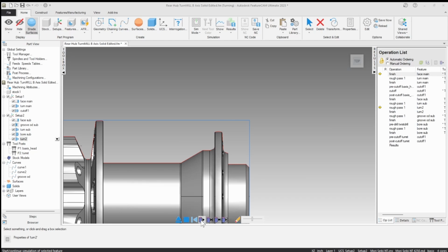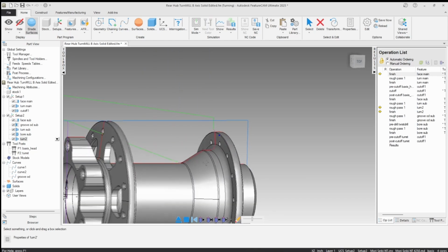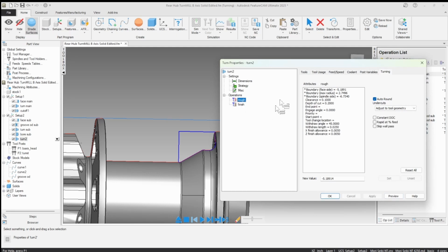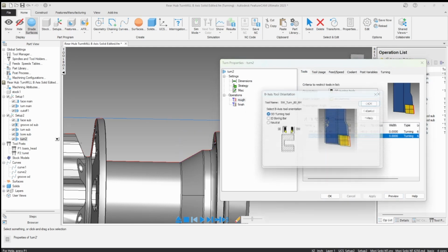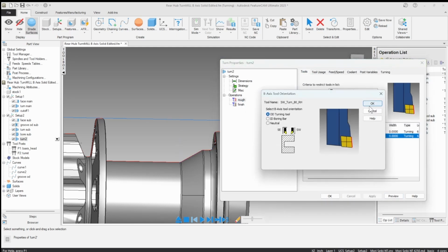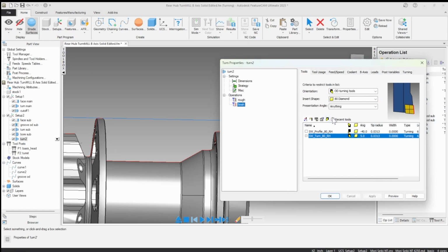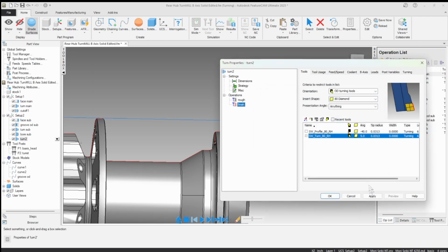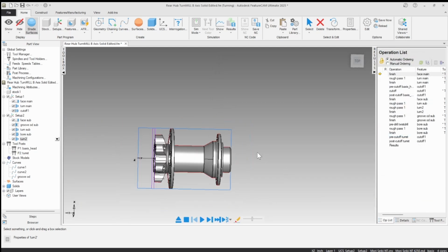And we don't really need the B-axis on this one, so we'll let it do its thing, but maybe we want to do that. So we'll rough it out vertically. So just as a reminder, there's the B-axis button. We'll do OD and the finish pass. Maybe I'll tilt that a little bit. I'll say neutral and do like 80 degrees. So in this case, since we're going the opposite, we're going basically the other direction, we would want like 100, right? So vertical is 90. All right, so that's how that works.